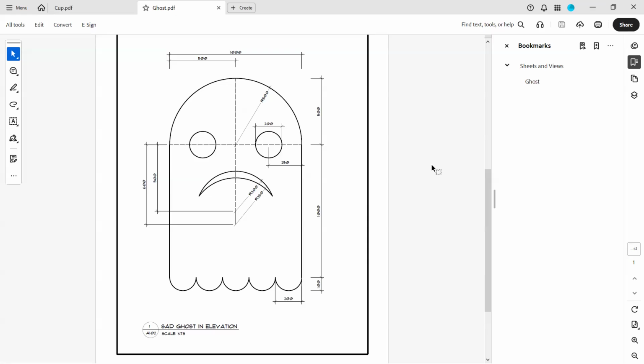Question. Offset creates parallel projection, right? Yeah. So O, enter. Let's say you have a line here. You want a parallel projection, you say O, enter. It asks you, so always communicate, it asks you for the distance. So how far do you want it away? Let's say 400.